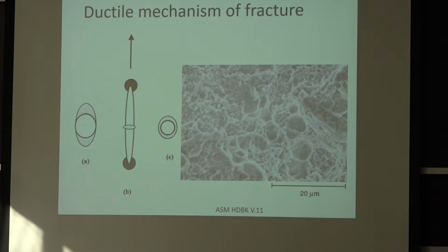So it was just a little bit of a side note that, in addition to looking with the naked eye at the fracture surface and seeing all those lines, you can go a lot deeper, and you have to bring it to the microscope. This is approximately 500 to let's say 2000x magnification, sometimes higher depending on the material, and you typically use an electron microscope, because if you try to do it on an optical microscope, it gets too blurry.